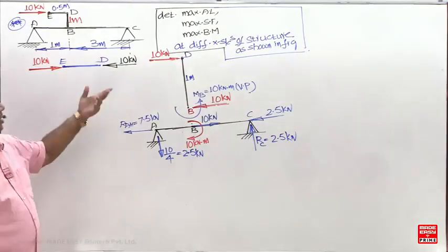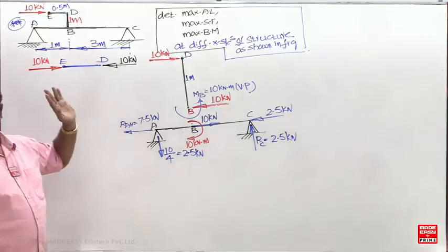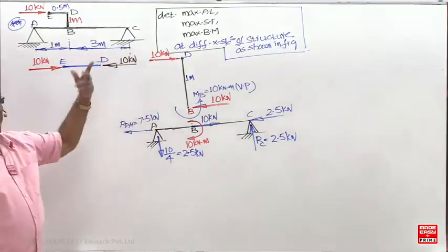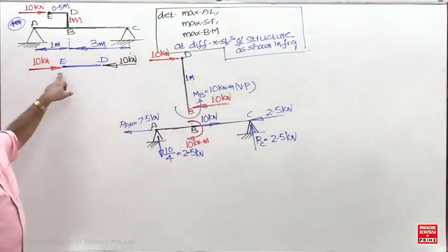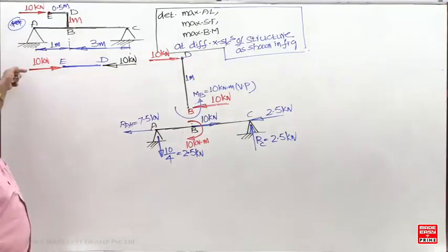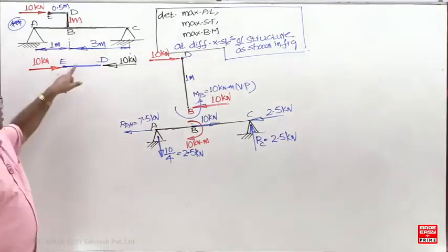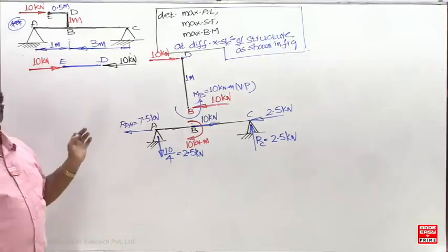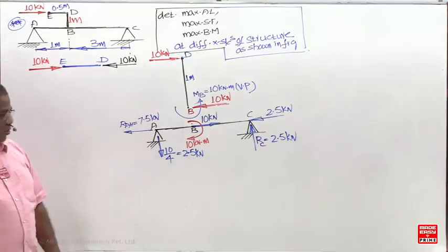Now, without drawing the diagram, can you directly give the loads at different cross sections at E? Is it a junction or non-junction? Non-junction. Here only which load is there? Constant point load. So at E you are getting only shear force; the remaining three loads are 0.